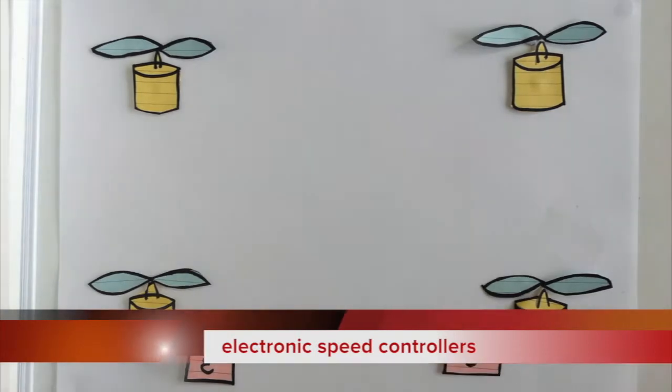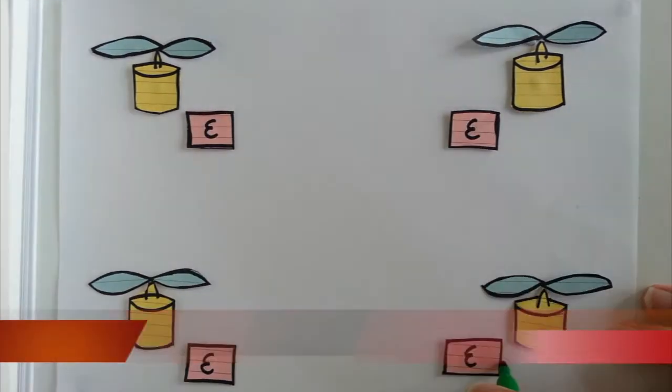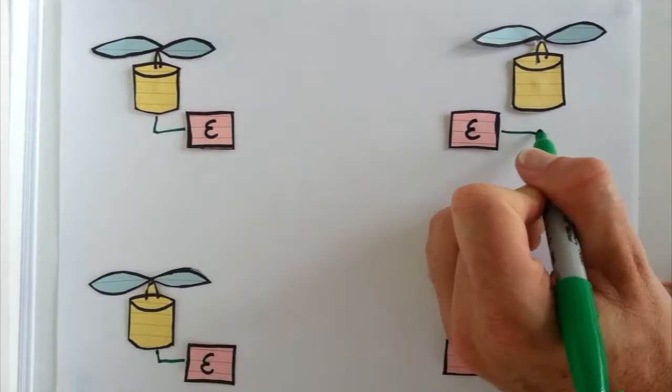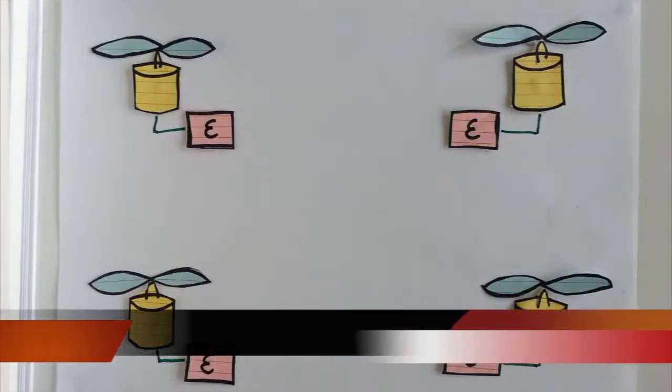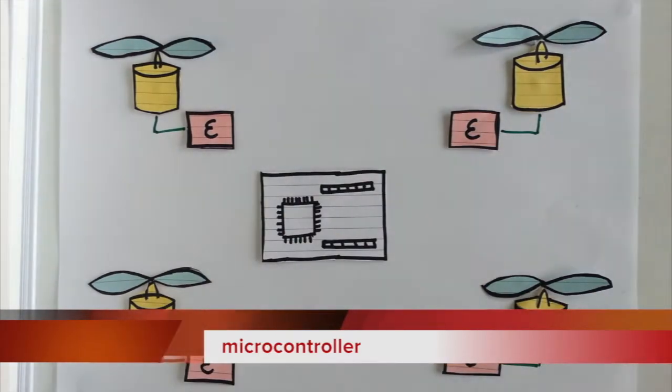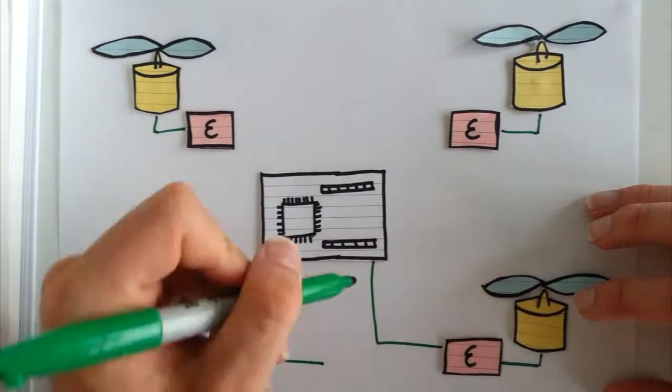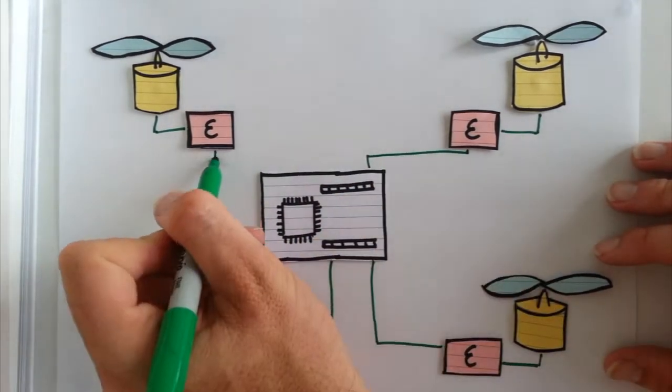As the motor starts to spin, the electromagnets must be turned on and off at exactly the right time so the motor doesn't suddenly jolt to a stop. This responsibility is handled external to the motor by something called an electronic speed control. The ESC expects a digital signal representing throttle. A microcontroller will be used to send the signal.